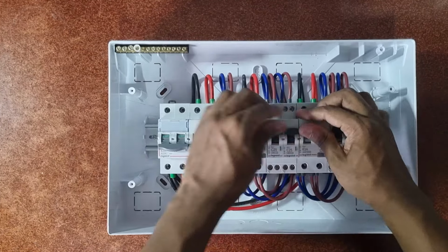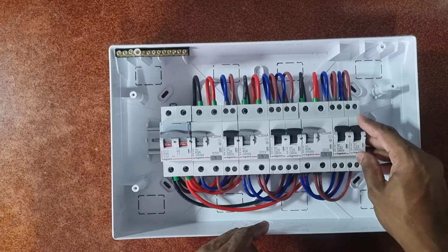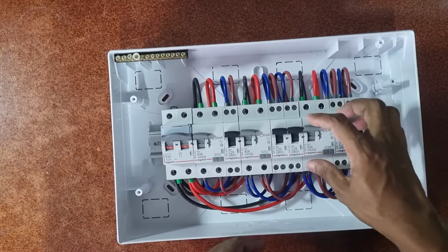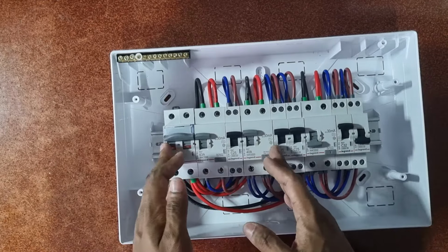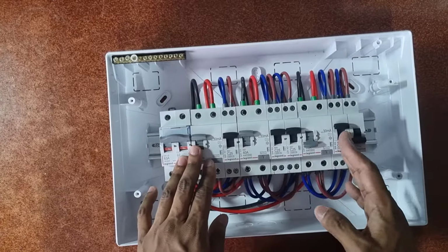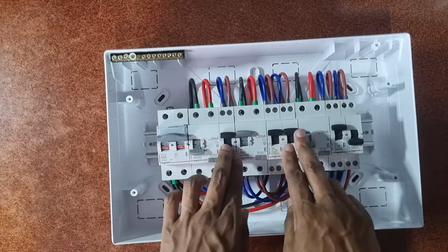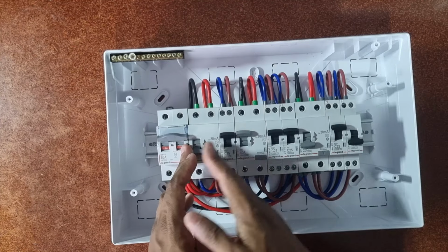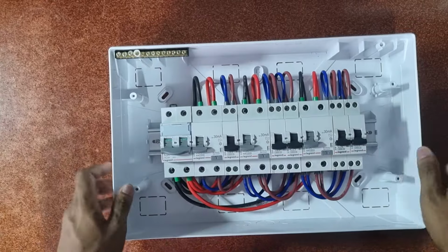So let's say everything is on, okay, and let's say this breaker here, there's a fault in that room, so when it trips, only one room will be switched off, the rest will still be on. Okay, so let's say I use only one RCD and then the rest are circuit breakers. So if the RCD trips, let's say all these 5 breakers were on the same RCD, so everything will be blackout.